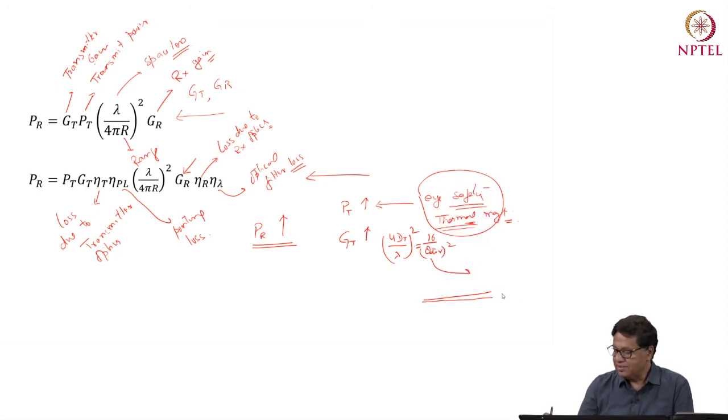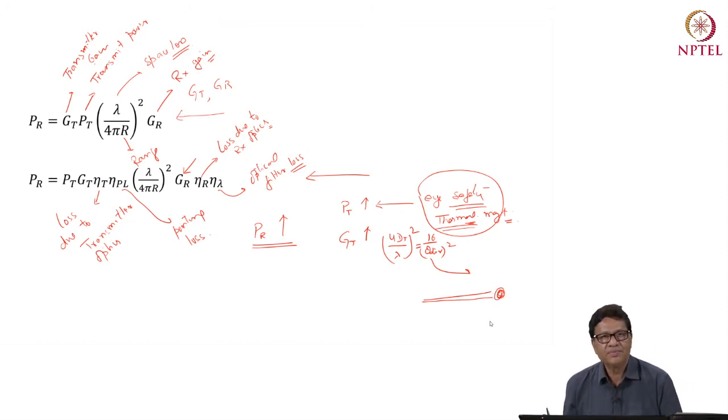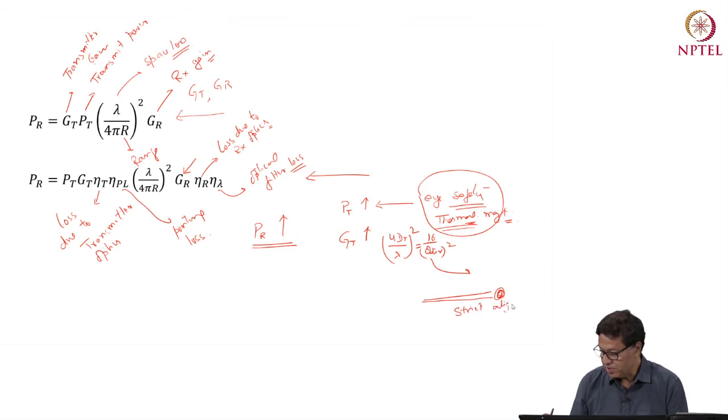and there's a receiver here, this alignment becomes very, very critical. Even if there is a mismatch of the alignment, you will not get any signal. So there is a limit up to which I can decrease theta divergence. A lower value of theta divergence means I require strict alignment, which may not be possible in practice. So again, one has to work within a certain limit.